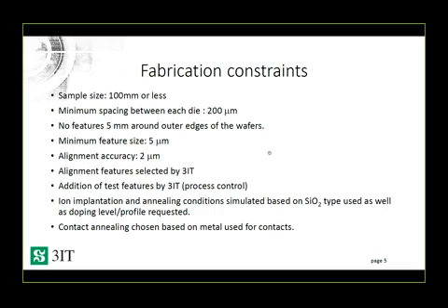We also add test features, typical TLMs. If the customer does not want test features specifically on their die, that's fine. We need real estate to put these test features, and we also have control process windows that we put, whether it be for controlling PCVD deposition layer or etching during the process without going into the dies per se. We put all these features outside the dies of the customer.